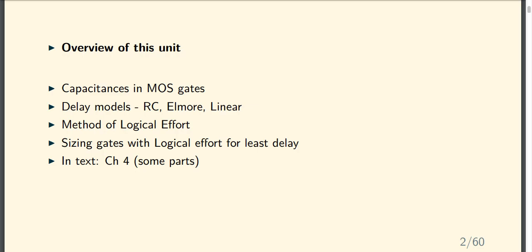And inductance also is there, but we will generally ignore the inductance because of a few reasons. One is inductance is very important, but it becomes significant only when we have very high speed circuits. So the effect of inductance can generally be neglected even when we are at the megahertz, close to gigahertz range. Also, inductances can be neglected. So most delays in the digital domain will be at the RC level itself.